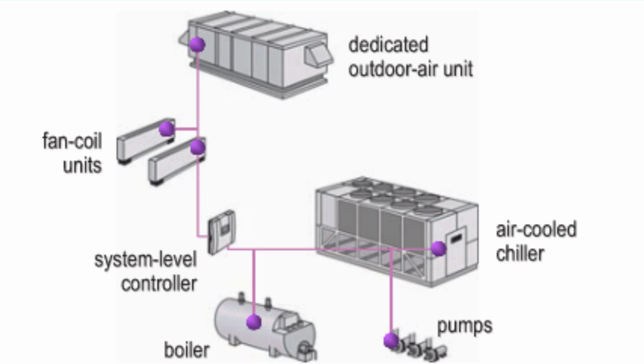System-level control is where the orchestra comes together. Imagine each unit controller as a musician. The system controller is the conductor, coordinating timing and balance. It manages modes like occupied, unoccupied, and morning warm-up, making sure chillers, boilers, and fans all work together. For example, it can ensure a cooling tower and boiler don't run at the same time, or that VAV boxes and air handlers adjust together. This coordination improves comfort and cuts wasted energy, turning multiple machines into one intelligent system.